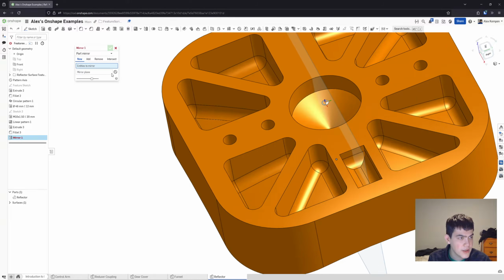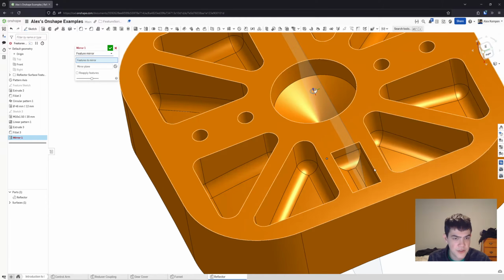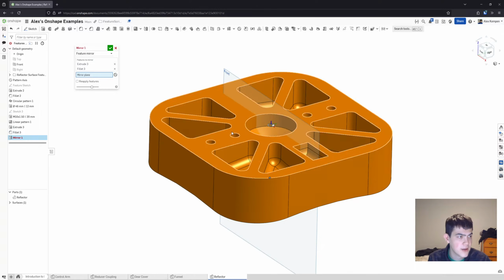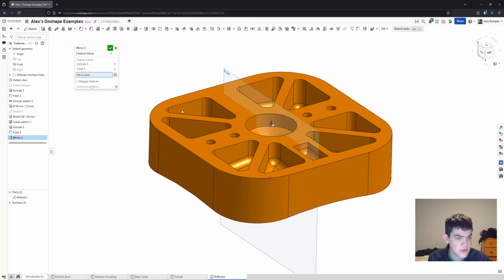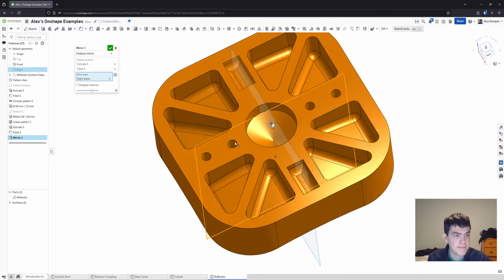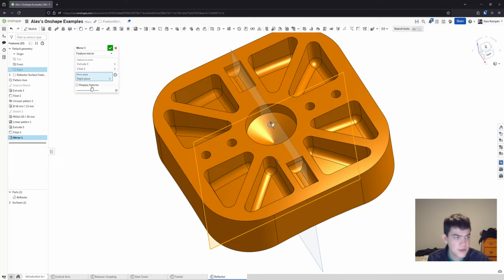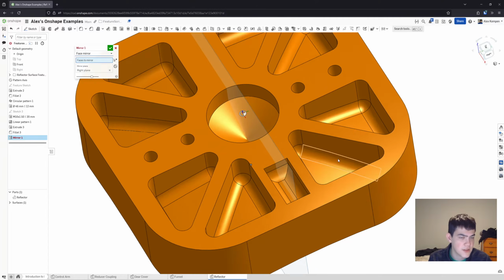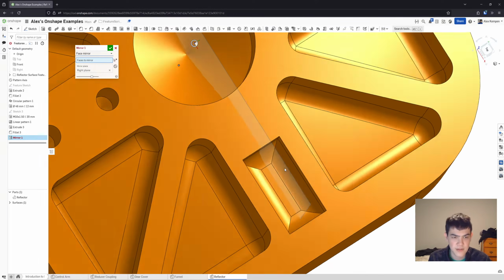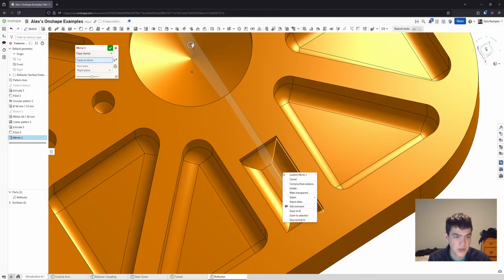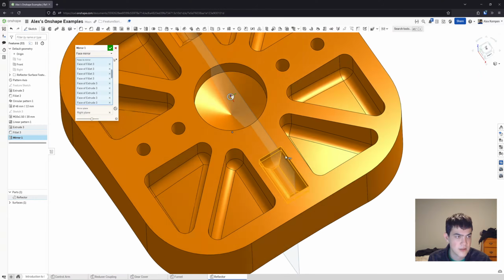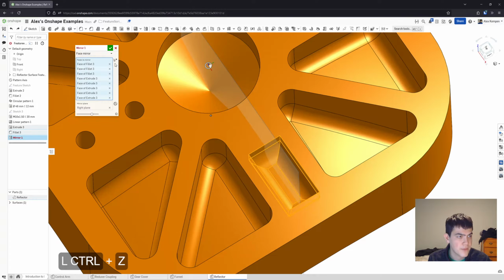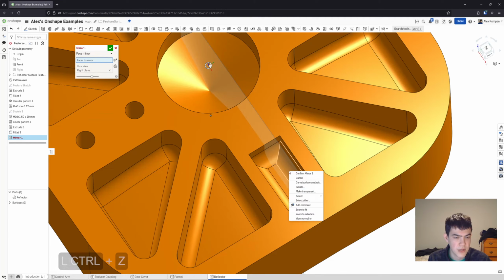So we'll do mirror. Here you could do a feature mirror and just select your fillet and your extrude. That would work perfectly fine. I can actually show that. So you just mirror like this. They're having you select the faces manually, which is fine too. So you could click all the faces. Obviously that's a lot of clicks. So they're showing right clicking, and then you can select pockets directly as an option. But they're showing the entire manual flow.